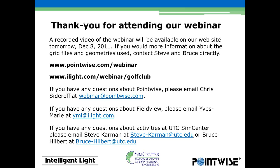Just a follow-up from Chandan Kumar on the cleaning process. He's asking, more specifically, how many operations did it take to actually clean up the model, like filling the holes, stitching meshes together, repairing missing geometry, et cetera? After it got into Pointwise, not a lot. I believe I put in 2 structured patches that I then converted into database or geometry elements, and just made sure they were smooth with the existing geometry that had come from the laser scanner post-processing package.